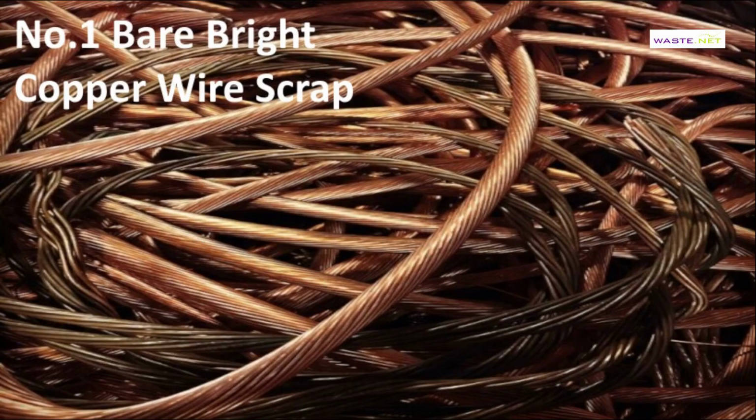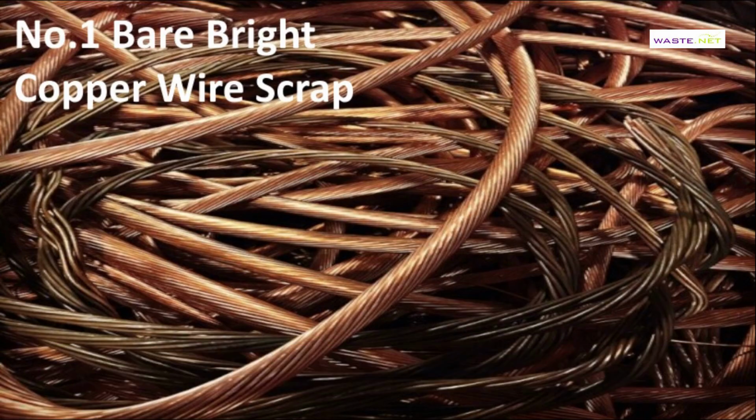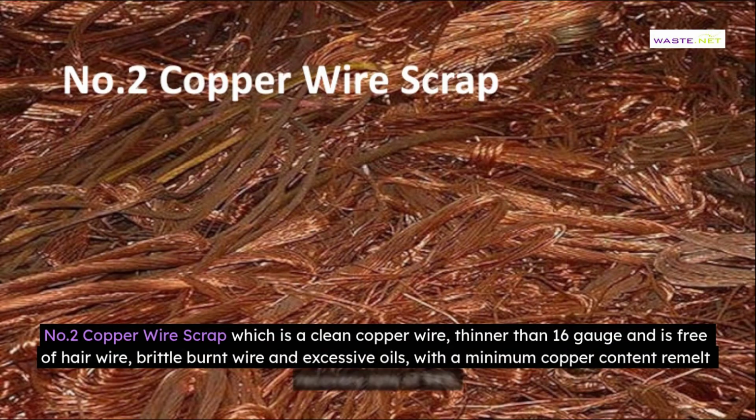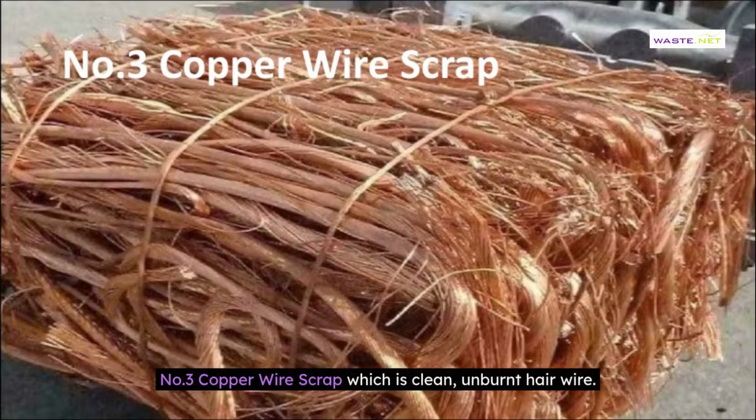These are clean unalloyed copper wire scrap, which are: number 1, bare bright copper wire scrap, commonly referred to as millberry, which is a thick wire of 16 gauge or thicker. Number 1, copper wire scrap that is 16 gauge or thicker but that is not necessarily bright or shiny. Number 2, copper wire scrap, which is a clean copper wire, thinner than 16 gauge and is free of hair wire, brittle burnt wire, and excessive oils, with a minimum copper content remelt recovery rate of 94%. Number 3, copper wire scrap, which is clean, unburnt hair wire.